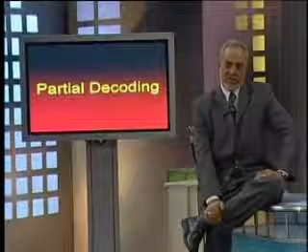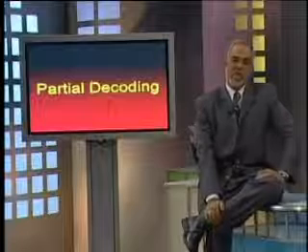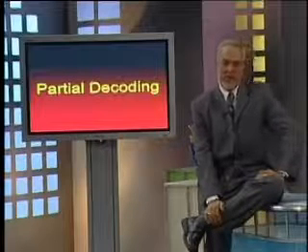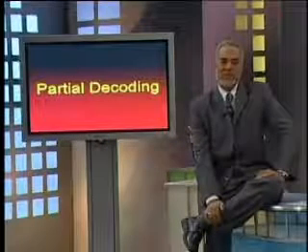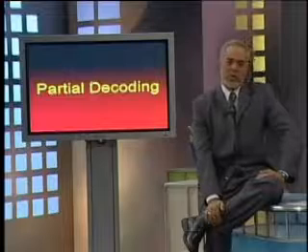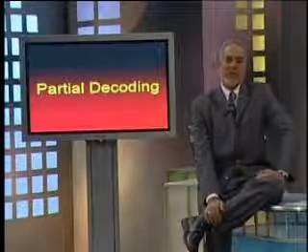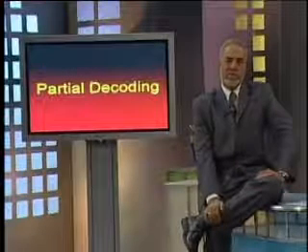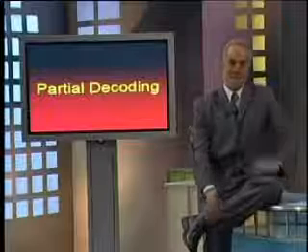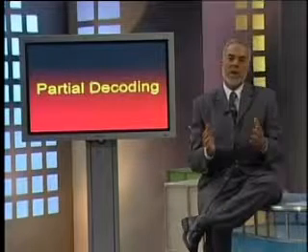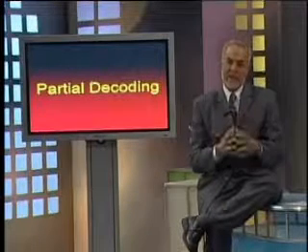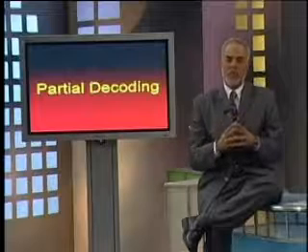Take a very simple example. We do have a memory mapped I/O. Nevertheless, as in the case of non-memory mapped I/O, we do not use the upper 8 bits of the address line. So we use only from A0 up to A7 as an input. What would be the result?